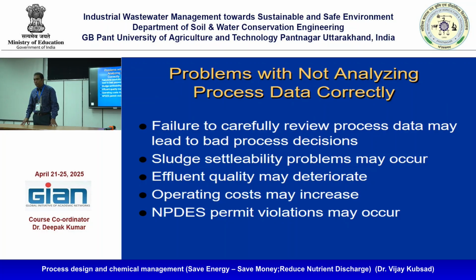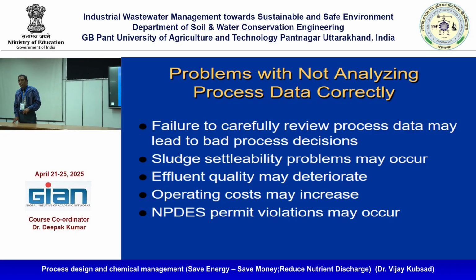See, we were talking about one example. If there was TDS, we suddenly have to move to another kind of treatment. You cannot expect that activated sludge will remove TDS if it is dissolved, because you are not measuring the TDS at the source, at the influent, because it is not mentioned in your authorization. See, that is not my fault, but the effluent quality is not met. But if nothing is measured, no measurement, no pollution.